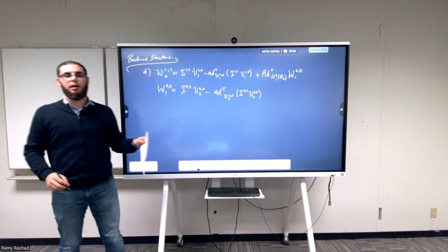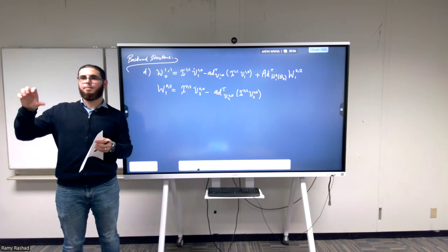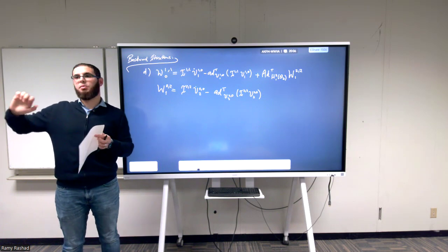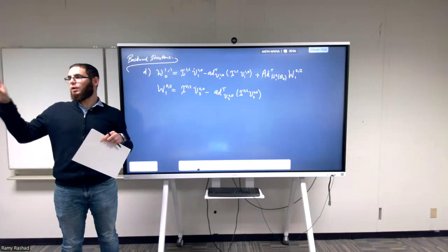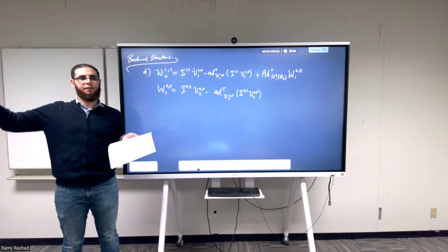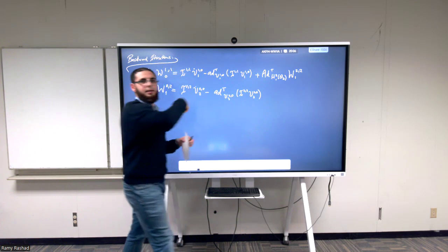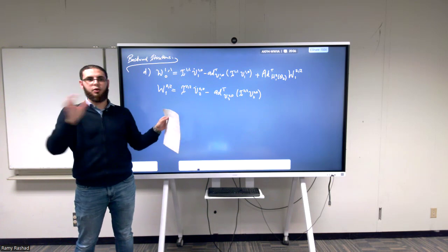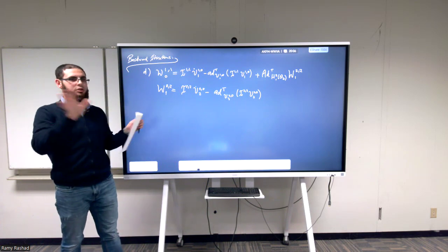And there's nothing else. Let's imagine, just for a second, that the 2-link manipulator is pushing on something, because this is a robot. It's going to be pushing on a wall, drawing something, or it has a tool doing something. The tip of the robot is what we call the end effector. So you also have a wrench on the end effector, and you're going to have an extra term there. This is what we discussed, that you can always add external wrenches in this way. We're not going to be doing it for now, so we just assume that the robot doesn't interact with anything. There's no gravity also. We didn't talk about gravity, so we don't have any extra terms.